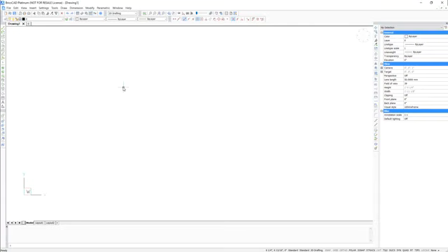So we'll use that profile template, those settings that I selected from that 2D drafting template. Okay, now before I forget, let me just quickly show you how to get that welcome window back. You turned it off, but if you want to get it back, you can use the Get Started command, and you can see down here at the bottom, I'm typing that in, Get Started. And right now it's off because I turned it off.